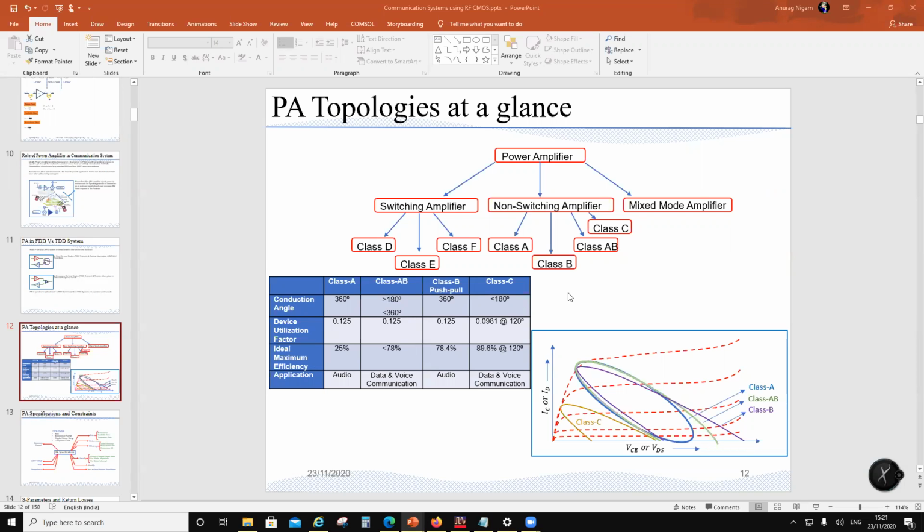Now, the restriction of a small transistor is it has got Vmax and Imax. So Vmax into Imax would be the power capability of a transistor. So if I take a topology and find out what is the maximum power I can deliver and divide it by the Pmax of a device, that will be called device utilization factor. So now I can compare various topologies for a given device utilization factor.